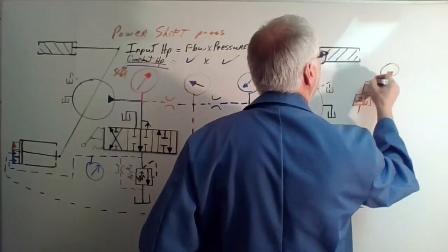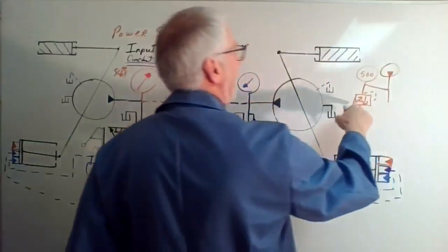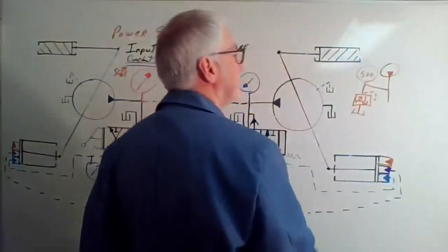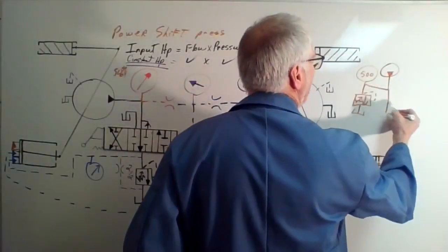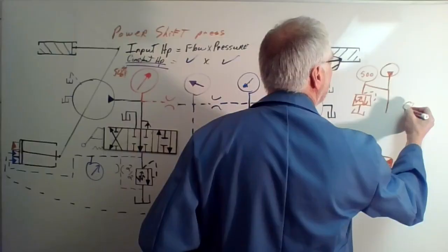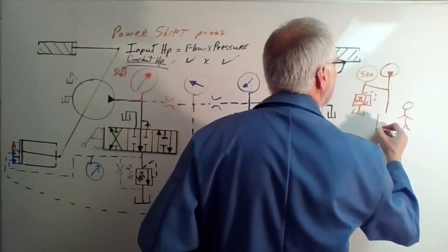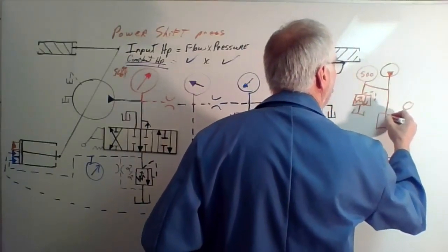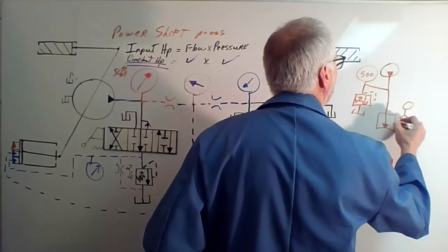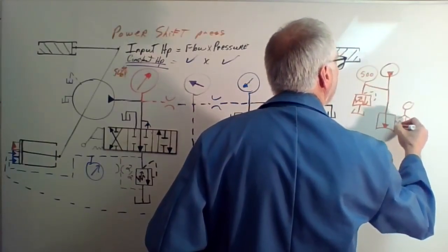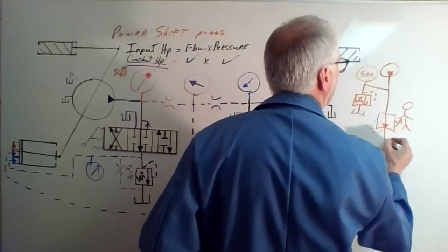So what I'm saying is, for all practical purposes, I have right here sitting about 500 psi, which I can use as a relief valve for a pilot system. So I have about 500 psi there. That's good. So if I was going to throw an operator in here and have the operator control this valve, so the operator can physically control that valve, which ultimately can send